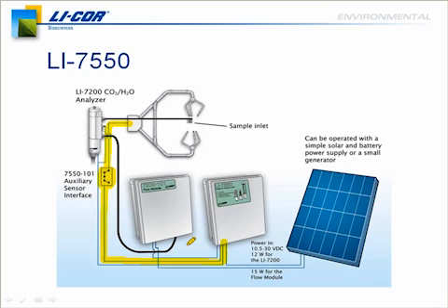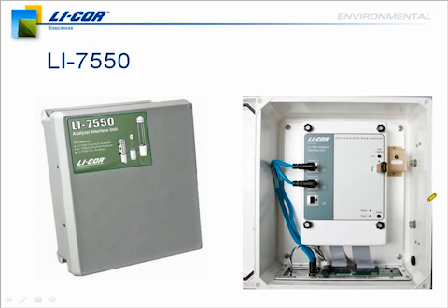The LI-7550 also has onboard data logging, and you'll see in this image on the right here there's a USB stick that you can insert for data collection. So now not only can you integrate CO2, water vapor, and sonic data, but you can log it right on board your gas analyzer now. It's a high-speed logging, and it does get everything synchronized up for you.